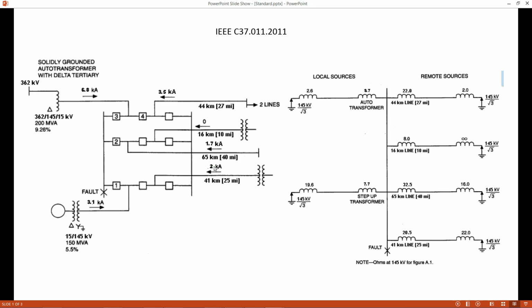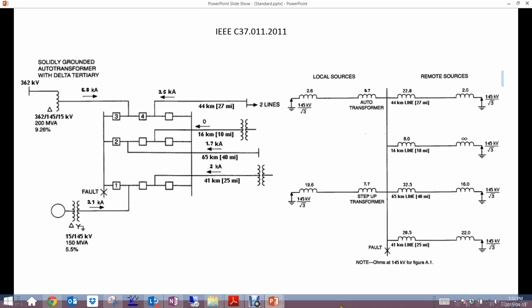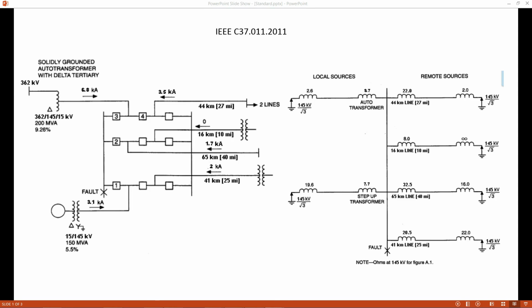So here in this guide, they provide some end calculation for the TRV, and so it will be interesting. We'll try to compare the result given by EMTP-RV, which uses very powerful models to reproduce the propagation in the line and to calculate the TRV, with the end calculation of the application guide. And we'll see that in the end EMTP-RV follows this standard and respects it, and can give even a more precise result if you build a stronger model.